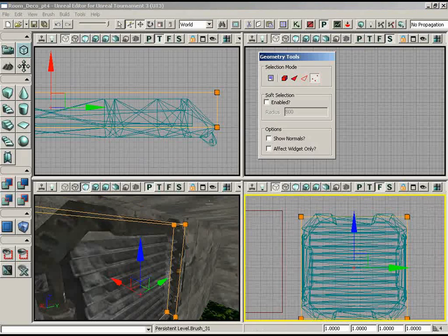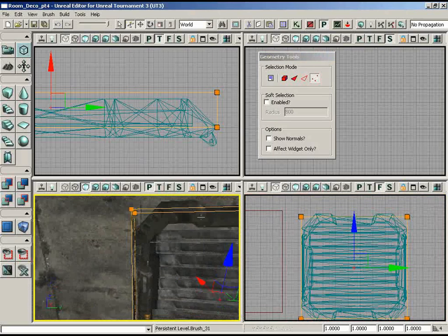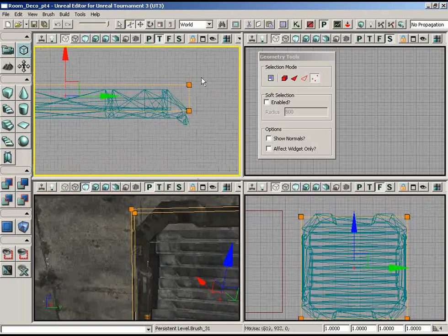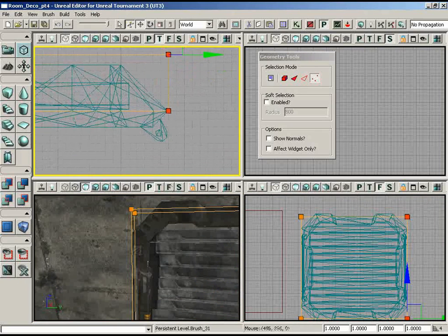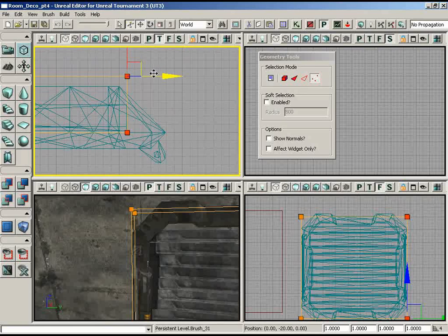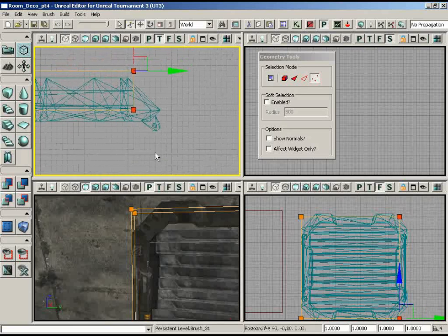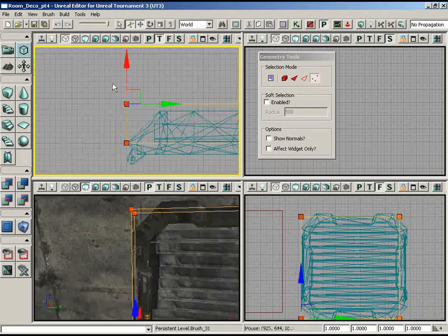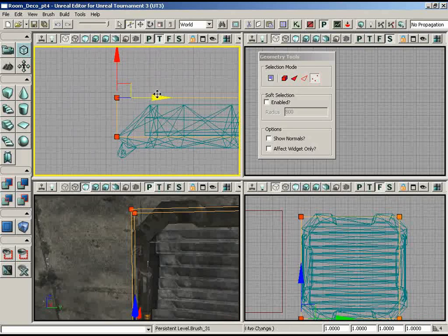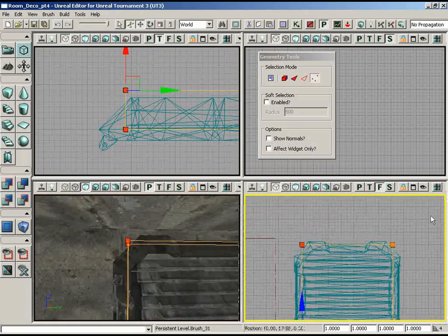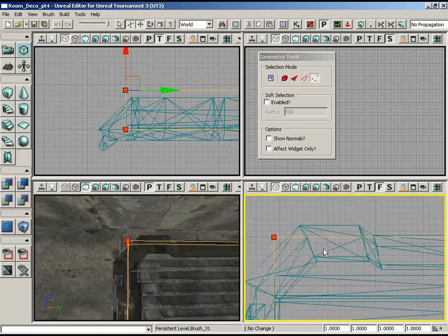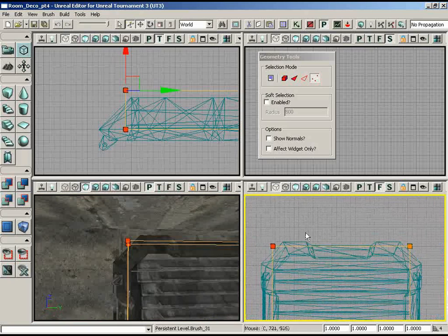And now to correct the problem where we have these triangles on the side, looking at it, it almost looks like these slats are represented by that square edge inside the mesh. So it's really like we could take the vertices all the way back to there on both sides, and then not have to worry about the problem with the triangles on the top. Let me zoom in here. Maybe a little bit anyways. Yeah, they need to be dropped down just a little bit.